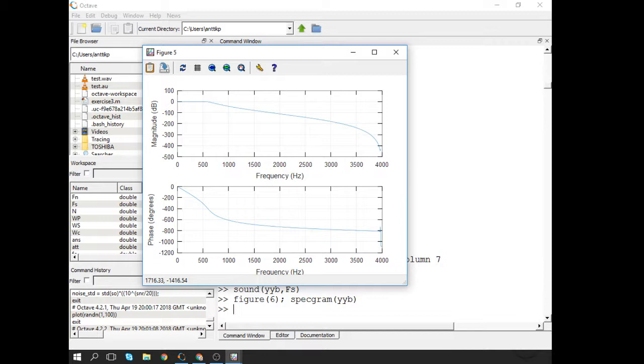So yeah, that's the main difference. Since if you do not need linear phase response, then you always get a more cost-efficient filter by taking an IIR filter. But of course, you can mess it up, but in principle.